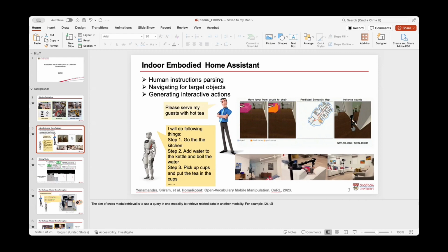let's say we have a knife here, it points in this direction and the hilt is in this direction. Although we have a table here and can navigate to every point, we can pick up the knife. But if the robot just stands in this position, it will grasp the point of the knife, so it's very dangerous. So we need to navigate to this location to grasp the knife. This is actually a bi-level or joint optimization of the mobile base and the robot arm, so the policy space is much larger than in fixed-base manipulation. So it's very challenging, and we are currently working on that.